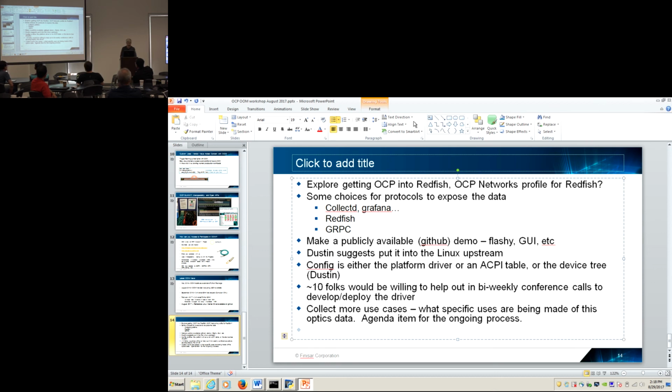Can you give me an example just to bring it to life? Tell me a customer you know of and something they do with the optical data. I think I have an example here. Customers care about the link budget between the fiber optic link, your remote access to the other end. How far is it? Is it multi-mode, single mode, or does it not matter, or is it just AOC? The end user, the customer, cares about the link budget between the link, right? And if they can use your parameters and ratings to figure out whether it's under a reasonable link budget, or for troubleshooting, if the optical link has a problem in the middle.